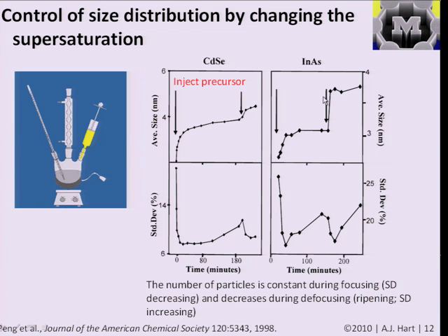And what's happening here is by increasing the relative supersaturation, we're going into a regime, and we'll see the bounds for this regime quantitatively in a little while, where the size distribution now starts to narrow. In other words, the dynamics of growth of particles, each one has its own size and growth rate, are changing such that the small ones are catching up to the big ones. But overall, they are all still growing. The average size is increasing. But this is the classical technique of managing the dynamics of growth after the dynamics of nucleation happen.